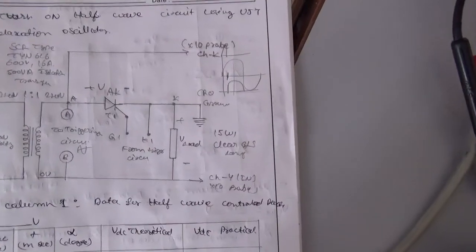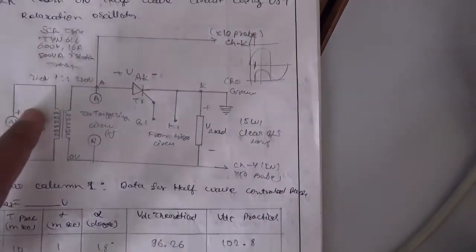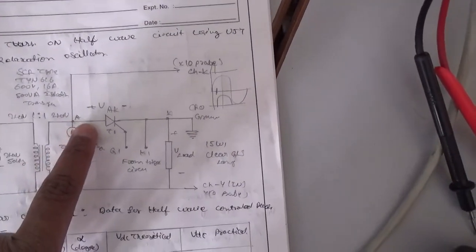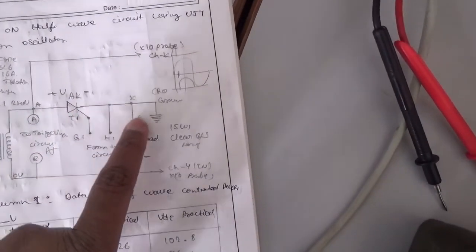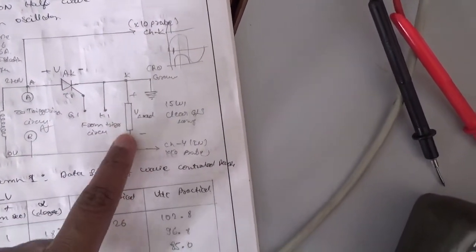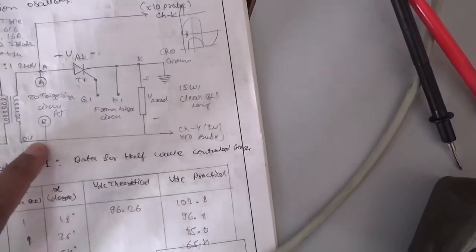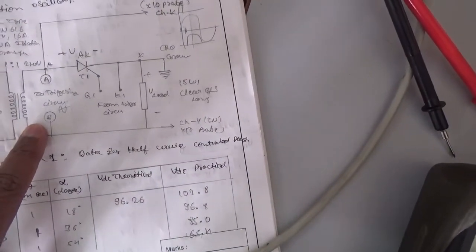So consider the power circuit shown here. The phase is fed to the anode of the SCR. Cathode is connected to the load. Load we are using is a bulb. And then another point of the bulb is fed back to the neutral. So we do the same connections.